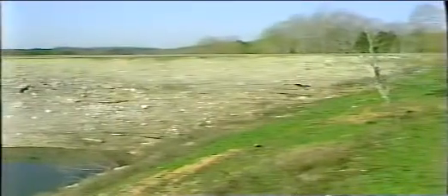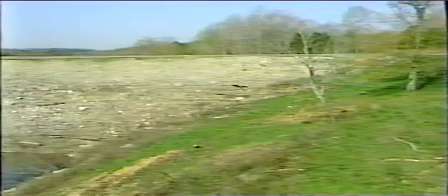Also look for depressions and sinkholes, animal burrows, and deep-rooted vegetation close to the dam that could provide pathways for seepage. It's unlikely you will ever see a whirlpool in the reservoir. However, whirlpools do indicate a heavy concentrated flow from the reservoir and are a serious condition, especially if they are near the dam. Report any whirlpools immediately.